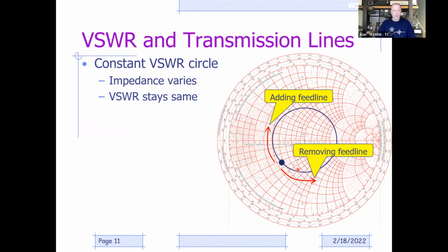But you might also say, well, I've got an automatic antenna tuner in my rig, and it doesn't like tuning on 75 meters. But if I add 5 feet of coax, it does tune fine. So it must change the SWR, right? It's going from one SWR that it doesn't like to a different SWR that it can tune to. The reality is it's not changing the SWR. It's just changing the particular complex impedance that's being presented. Your tuner might have a hard time matching an impedance that's here, but might not have a hard time matching an impedance that's here. But it's still the same SWR. All these interesting little facts come out when you start studying transmission lines and feed line lengths.